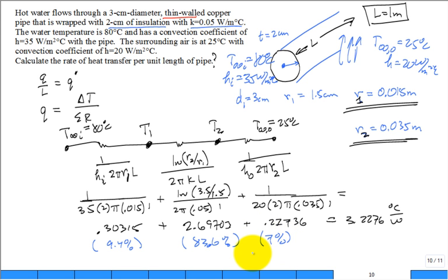Okay. So you could probably increase the thickness of that insulation some more and cut down even further on the rate of heat transfer. So we calculate Q, which is delta T over R. It's 17.0 watts. And then we recall, oh, everything was per meter. So there's your final answer. Does that make sense? 17.0 watts per meter. So use the network to help get straight and do your bookkeeping.